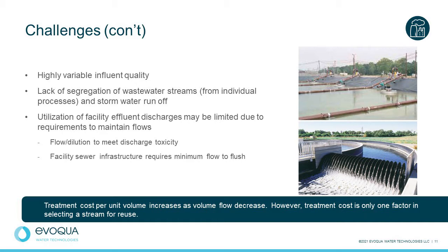Other examples of the realities that reuse initiatives often collide with are gravity flow underground sewers. They're subject to minimum flow designs when they were originally built. Reduction of flows due to reuse initiatives can inadvertently reduce flows below what is required to flush these structures. Water treatment processes themselves may generate waste streams or concentrate waste streams, and the waste disposal fate impacts discharge compliance.